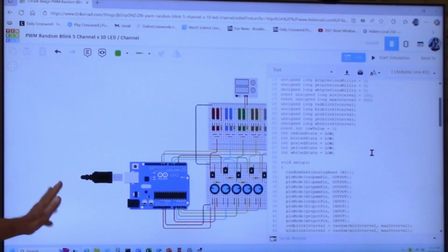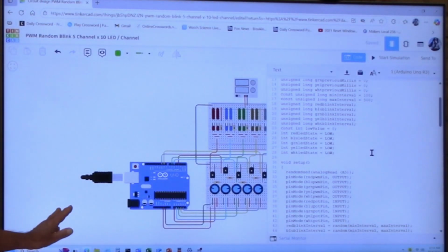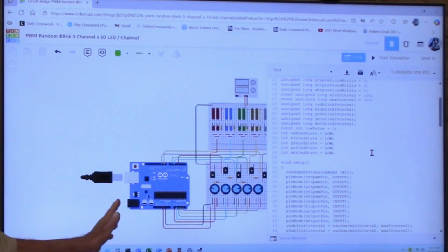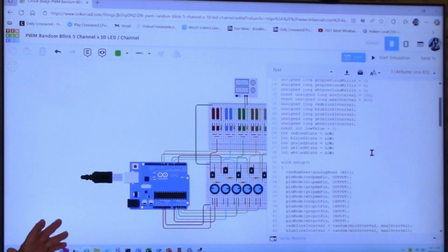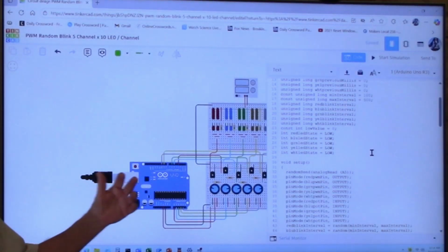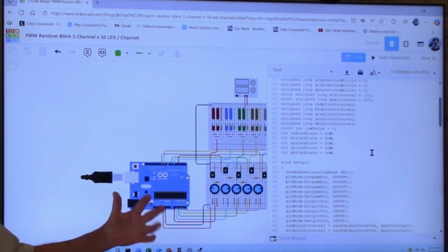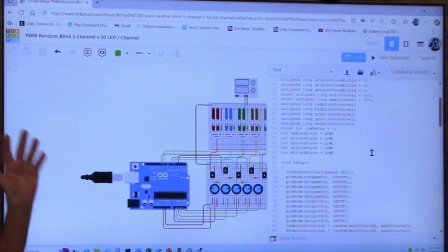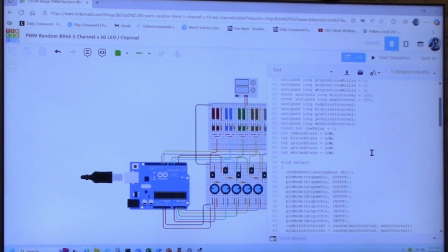Now, even though this thing has a random number, or a clock that we started, the millisecond clock, and the microsecond clock, which is 1,000 times as fast, it's finite in length, the number of bits. So the clock that you're choosing your millis and your functions with will overflow once every 41 days and something like that.